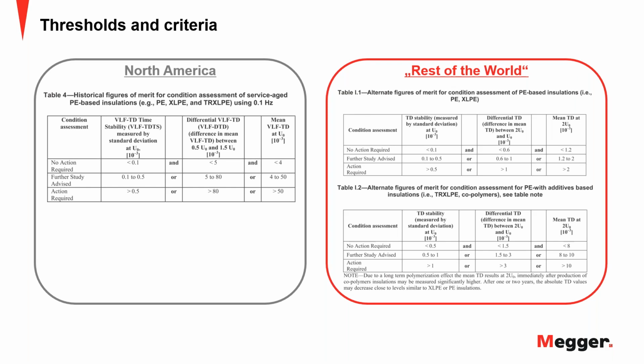They pretty much said, we sort the cable by importance. Less important cables will take actions on and try to monitor and fix the issue less often than more important cables, feeder cables. And then we determine a threshold where we're saying, okay, we know our jointing technology, splicing technology, remember there's cold shrink, heat shrink, slip on and whatnot.